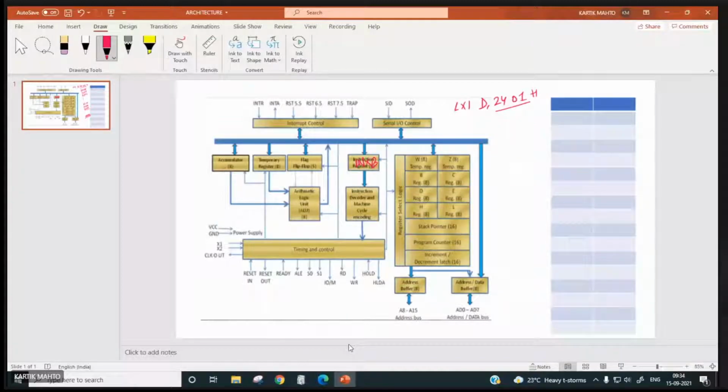We use the instruction DCX D, then MOV A,E, ORA D, JNZ loop. Is this point clear to you?